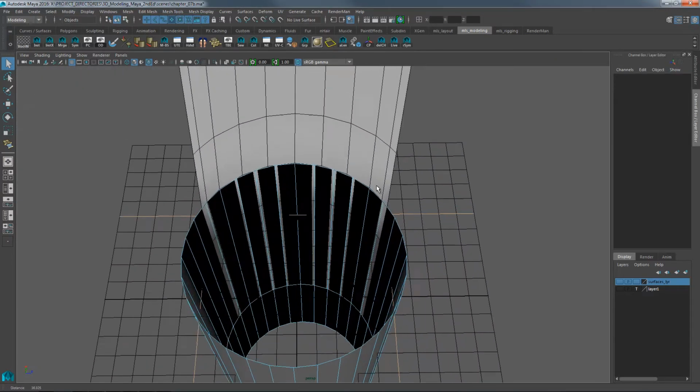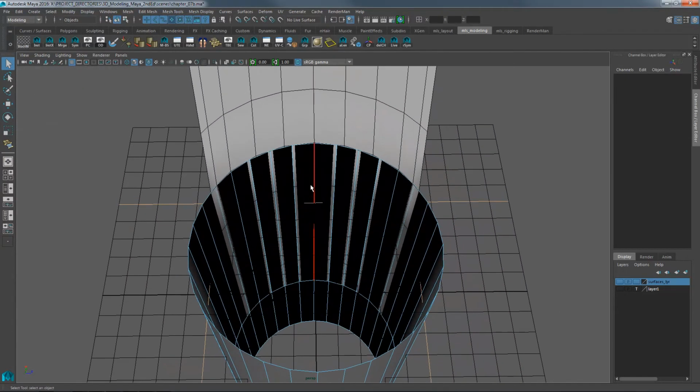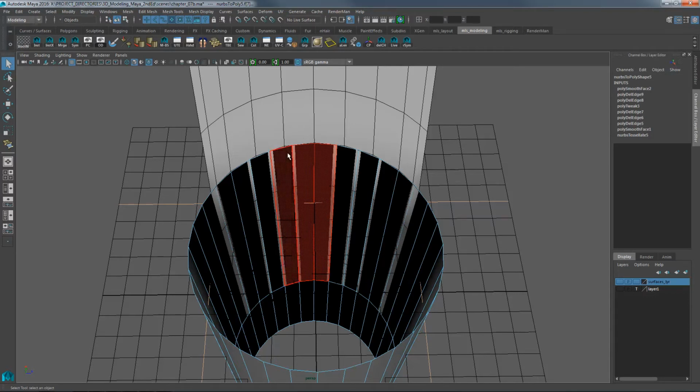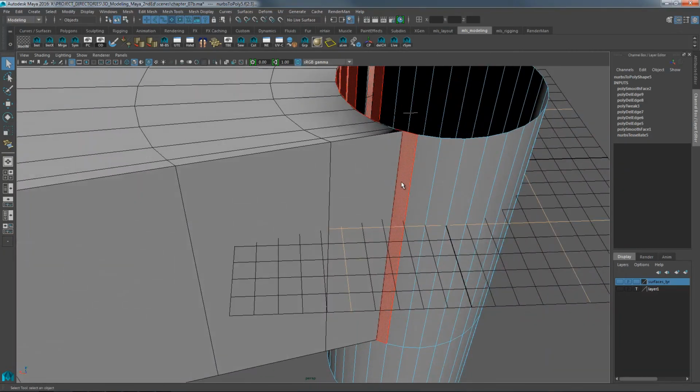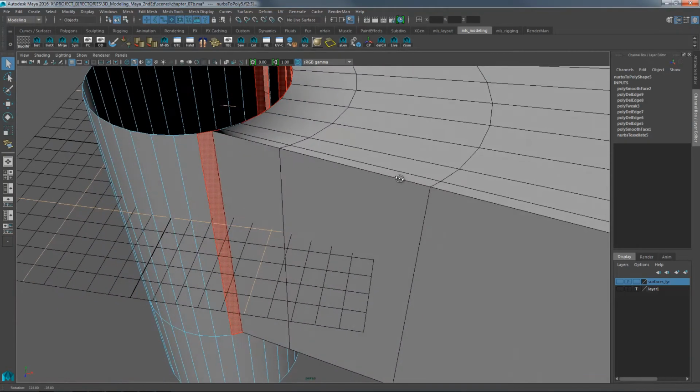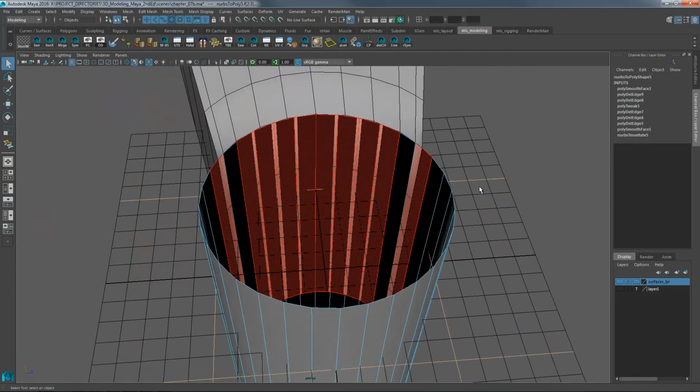Then look at the object right about from this angle, select two faces that I have selected at center, grow, not grow your selection, but add to your selection. So just hold Shift and add till you are one polygon out, right? Just exactly the same selection I have right here. Delete.